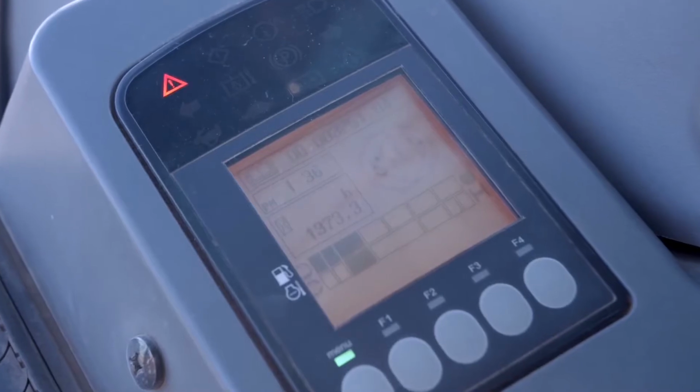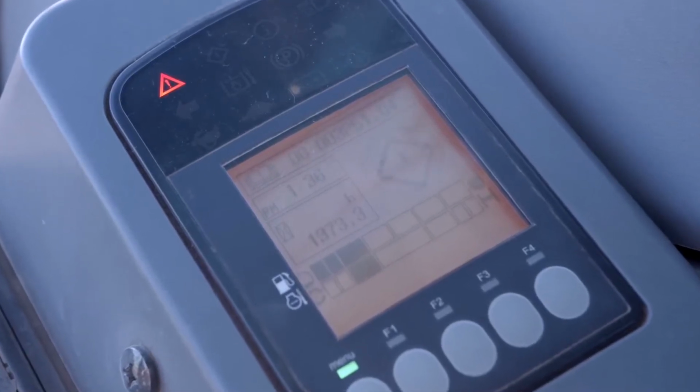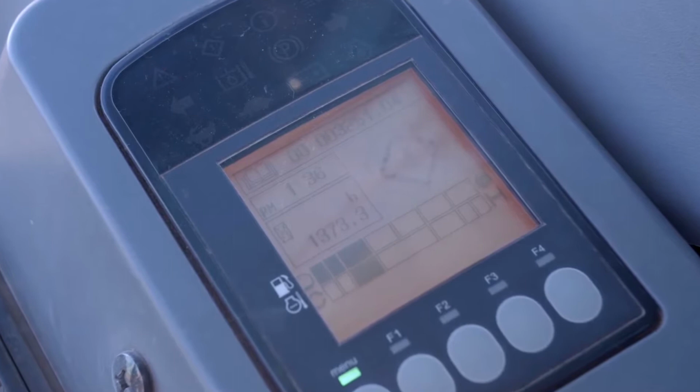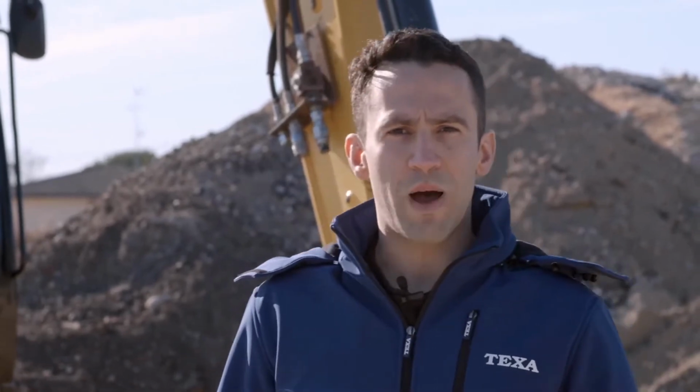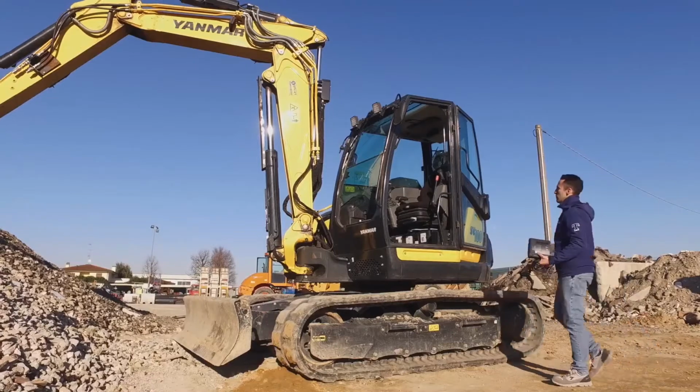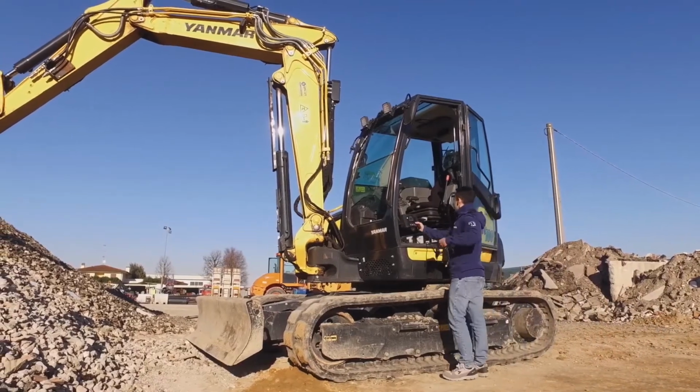In case of a malfunction, a warning light in the dashboard indicates that there is a fault in the after-treatment system that may require maintenance. If the regeneration is not carried out as soon as possible, the vehicle's power will be reduced by 15% and then after 2 hours by 50%.